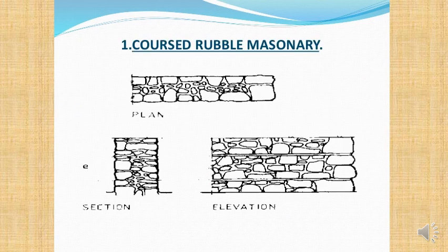So how do we arrange the rubble masonry? Well, I don't know if you can see there, but one of the key things is we try to collect the rocks which are most square and most regular, and we put them on the ends, and then we slowly build courses in horizontal lines out from them. And so the real irregular shaped rubble, we put that in the middle to fill in the gaps. And that's how you would go about building a rubble masonry wall.